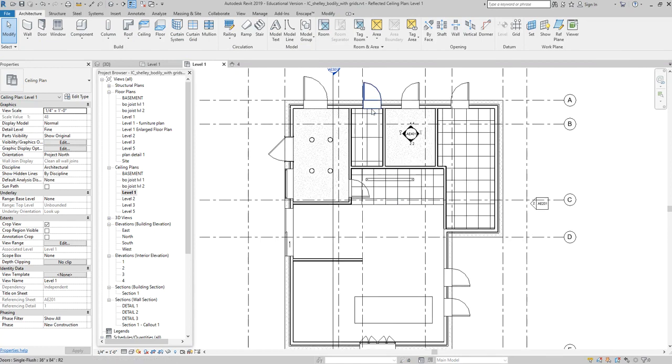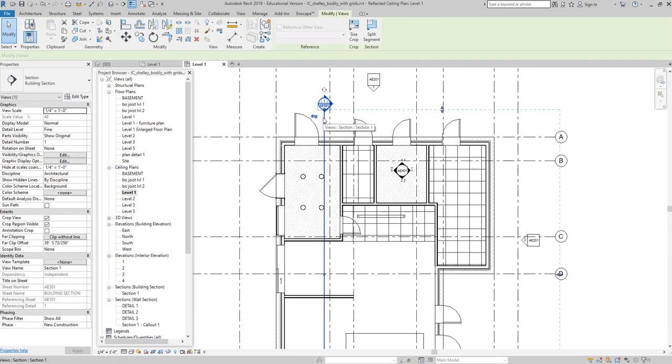All right, so we can create new ceiling types, we can edit their assemblies, we know how to auto sketch our ceilings, we know how to sketch our ceilings, we know that ceilings have a default 8-foot offset, but that we can go into sectional view or override that by typing it in. I think I said this, but lights host to Revit ceilings. Anything that is defined to host to a ceiling will host to a ceiling.